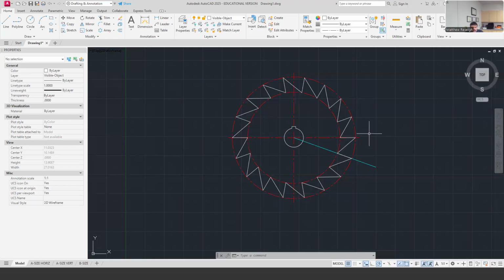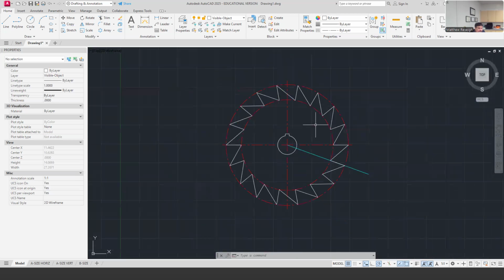to utilize materials as well as they can, bundling parts together on sheets. Of course, parts are all mixed up on those, and it's somebody's job to keep track of it. A lot of lasers will etch part numbers on there so they don't get lost in the mix, little parts, big parts. Sometimes nesting is somebody's all-day job, and maybe AI will take over that at some point. But currently they make software packages for cutting equipment that easily import these DXF files, and somebody has to arrange them on sheets to maximize productivity, using materials well.